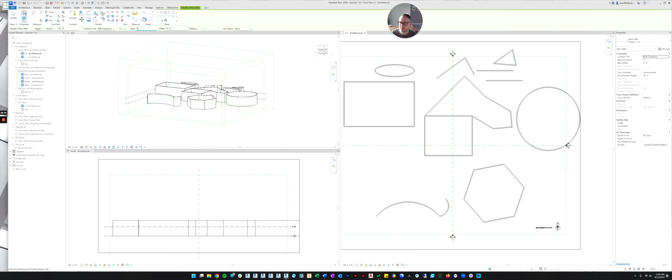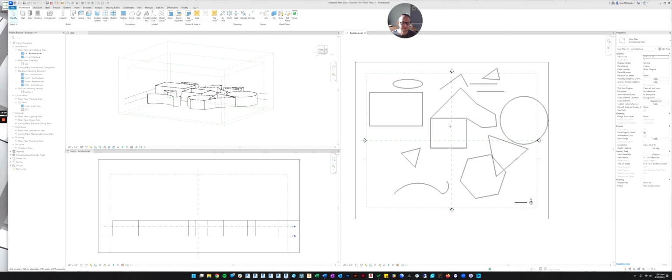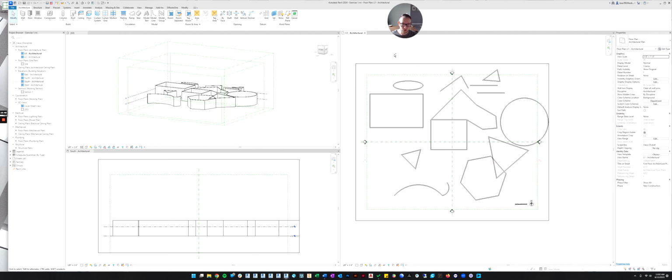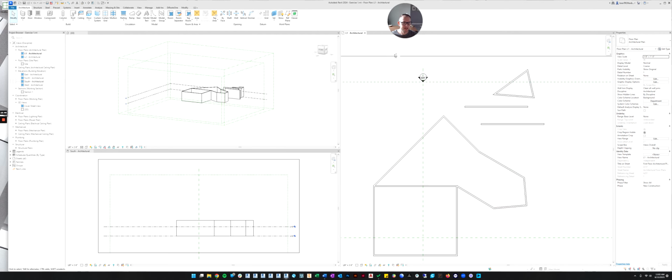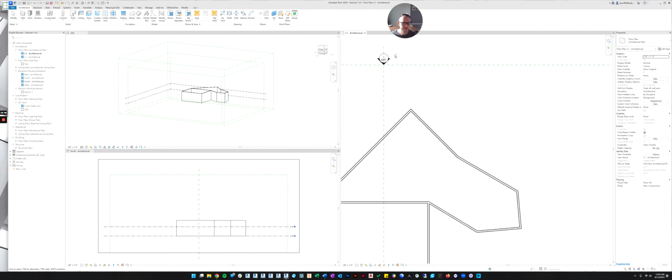If we only want 3 sides because we want a triangle, we can modify that up there and then click and it will do 3 sides. So sometimes pay attention to this little line right here, because it can modify the command that you're in. All right, so I'm going to hit Control Z to undo all of this and get us back to a clean looking view.